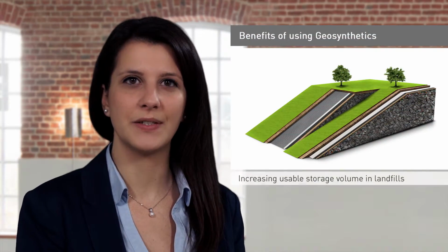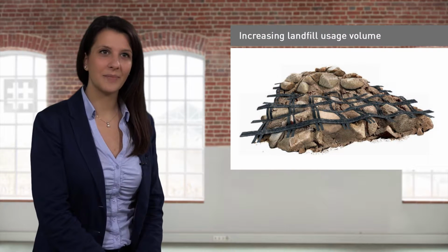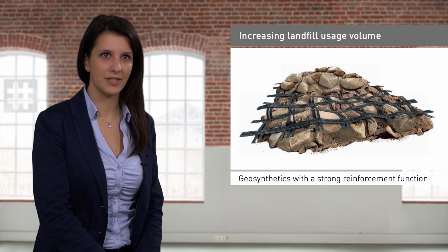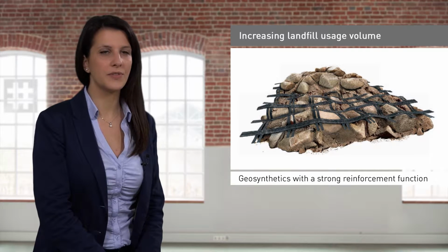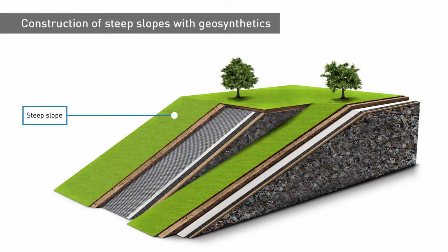Moreover, thanks to their thinness, geosynthetics allow the increase of the volume capacity of the landfill. This volume can be further increased through the use of a particular class of geosynthetics, namely those which function as a reinforcement. These materials have a high tensile strength and enable the construction of side slopes with steep inclinations.